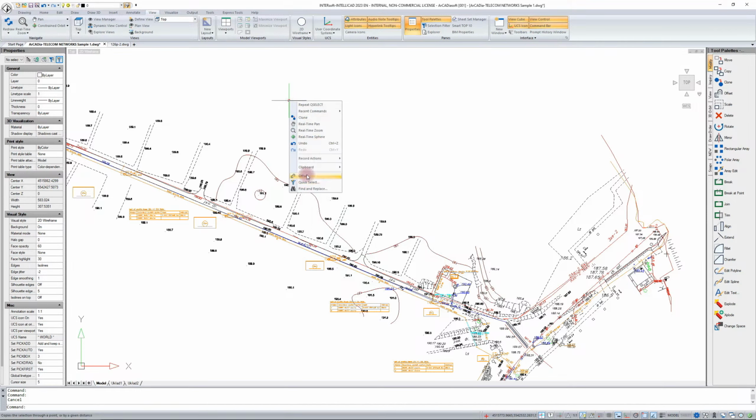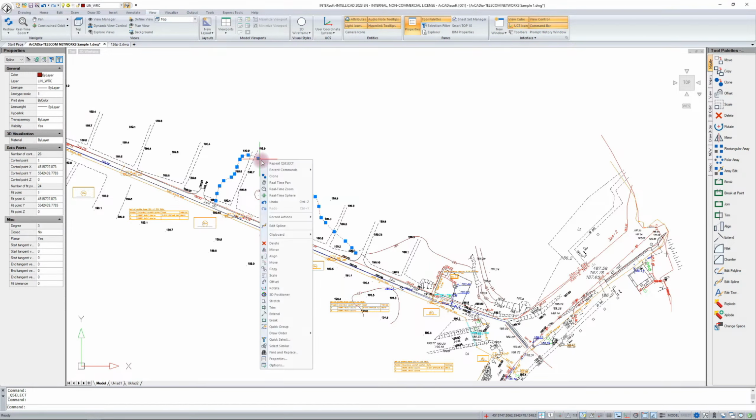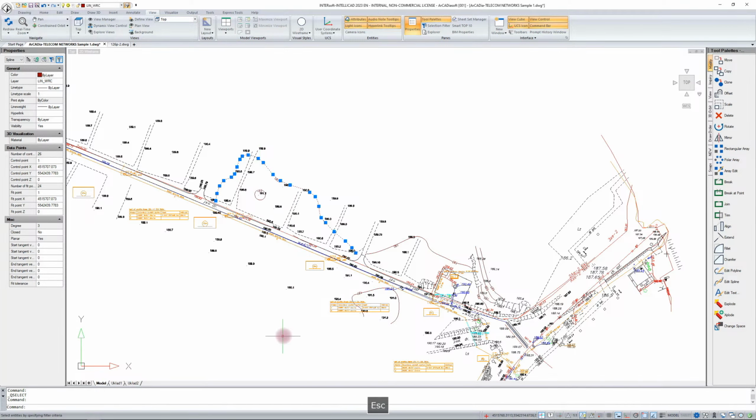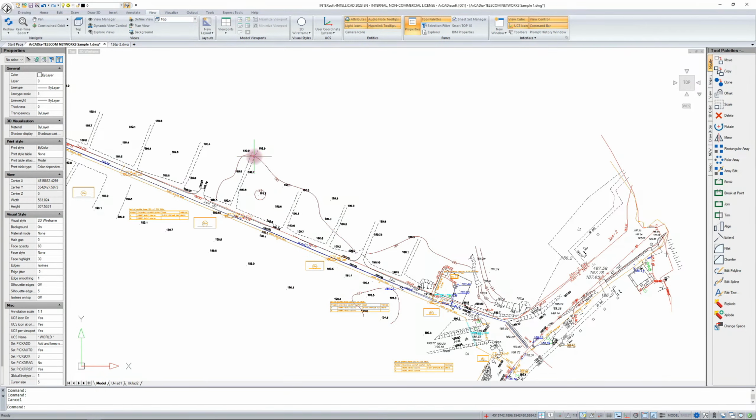And that's why I'll remind you that it is either under the right mouse button or simply in the list, that is, in the context menu that was talked about at the beginning. The option will be available here if, of course, we have not changed this context menu. If you select an item and click the right mouse button, you'll also find the option in the context menu. Another way to invoke quick selection is through the icon in the Properties window here on the right. We use this option to quickly find elements in a drawing for their modification, deletion, or counting, for example.